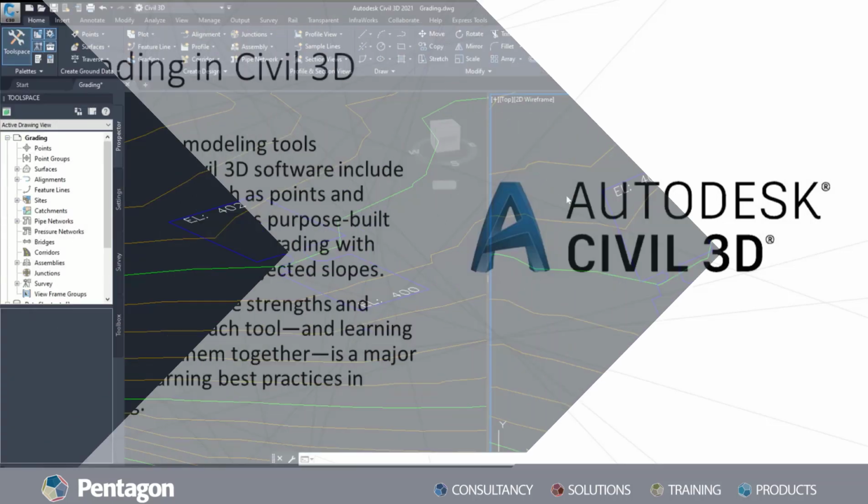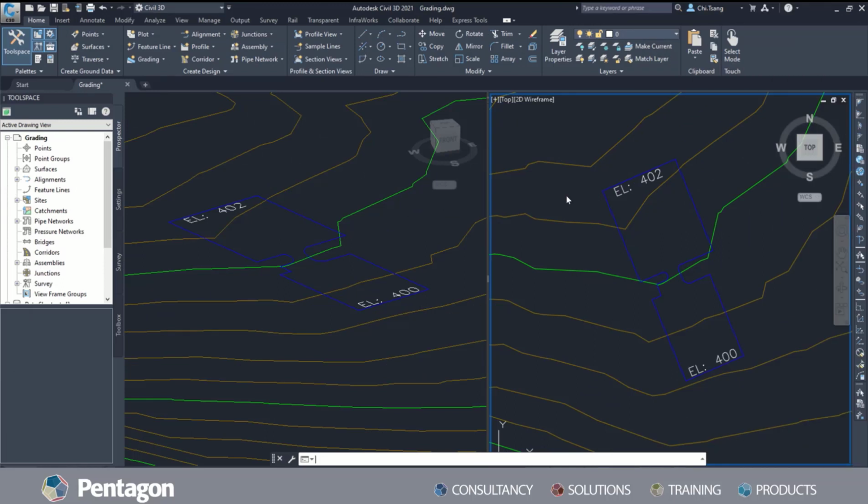So let's begin. First, we're going to create a stepped offset line. To start off, we are going to type in the command offset, gap type. By default, it goes by 0, so we're just going to go with 1. The offset gap type variable controls how potential gaps between segments are treated when closed polylines, such as this building pad feature line, are offset.